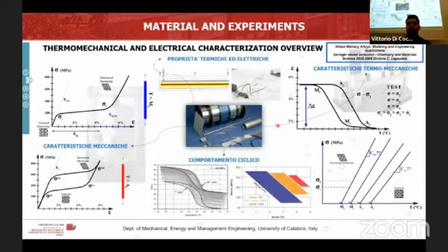To predict the behavior of this particular material, a lot of characterization is necessary, but in this work we are focused only on obtaining the mechanical properties of the two different phases by conducting two types of tensile tests. One when the temperature is less than martensite finish, and one when the temperature is above the austenite finish. Another aspect that we are interested in is the connection between the transformation temperature and the applied stress on the SMA material. This can be done by obtaining the phase diagram through some constant stress recovery tests.